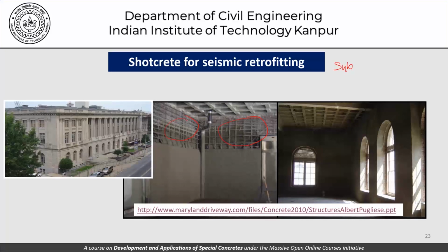So one advantage of using shotcrete in the repair works especially is that it works with any of the substrate materials. We have seen examples where we had a steel pipe. We saw an example where it was a brick sewer lining. We have normal reinforced concrete kind of bridge structures, and we have a building kind of a structure where these panels could be again made of either brickwork or any other material that is locally available and has been used.